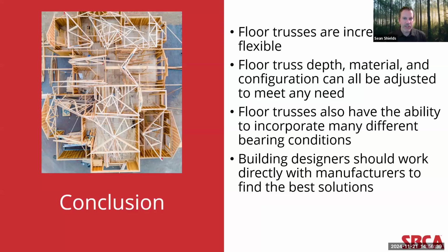Whether it's simply changing the depth of the floor truss or swapping out the material that the truss is made out of to a material that has a greater strength property, truss designers have almost an unlimited number of variables at their disposal that they can adjust to design floor trusses to meet any particular need a building designer has. As hopefully these 21 details illustrated, different floor truss configurations, support structures, and support locations, as well as bearing conditions, can be accommodated for any project.